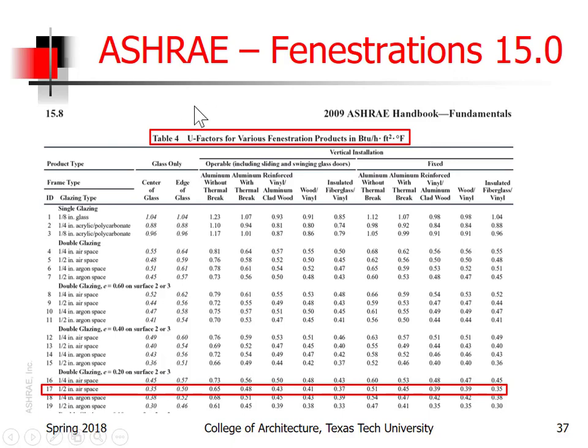The other is, of course, to go to the ASHRAE Handbook of Fundamentals and look at the U factors, and they have generic U factors for generic windows. Okay, but they'll be within 10% of the typical window. And you'll see, to read these, there's a whole series of charts, 2 or 3 pages of it. And the first thing is the glazing type. What type of glass are you using?